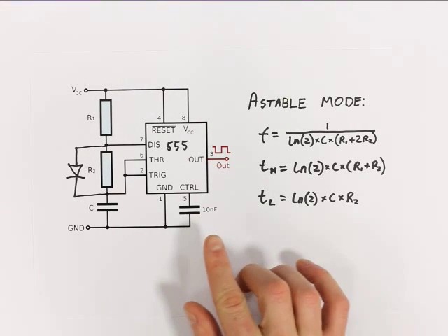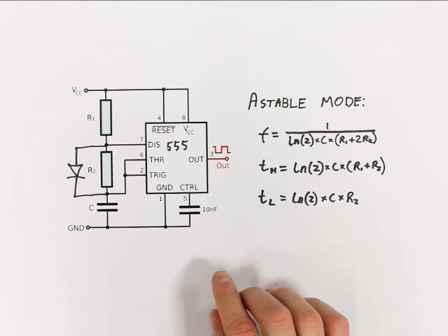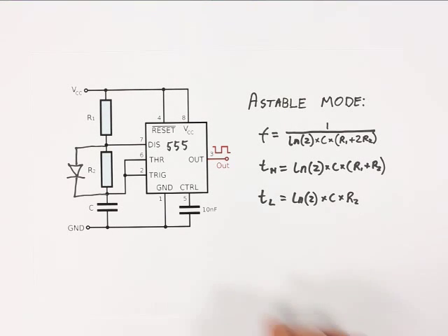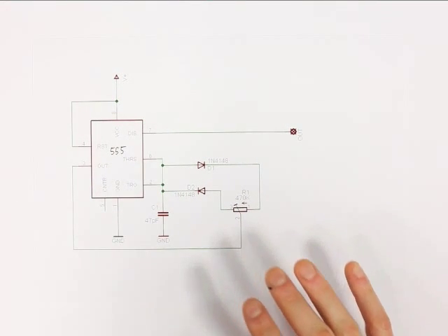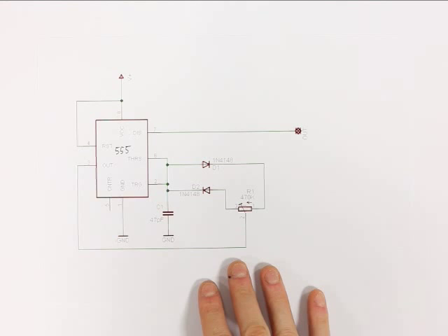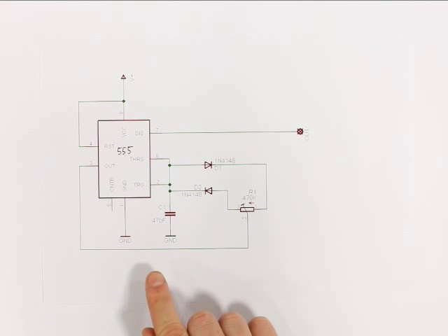Now, while this circuit is useful as an introduction to the 555, it isn't actually how I'm going to implement my PWM. Instead, I found a very interesting alternate use of the 555 timer. This circuit came from the same website that I got my constant current drive circuit diagram from, PCBheaven.com, in the article LED Driving and Control Methods by Giorgos Lazaridis.